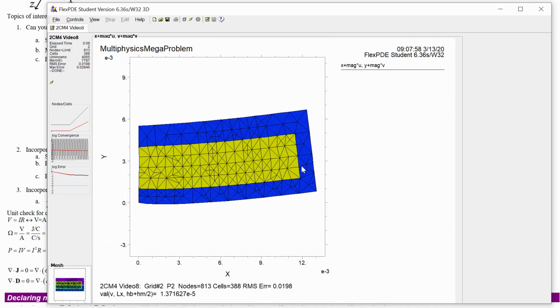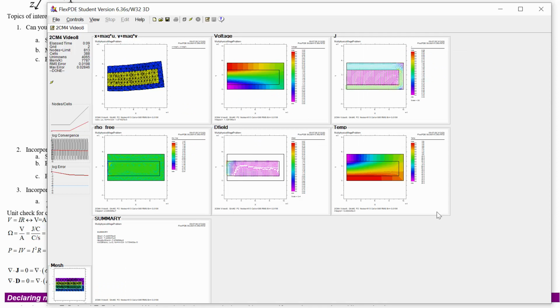The reason it bends up, even though we don't have any alpha difference, is because now we've got a temperature difference. The temperature at the bottom in this particular setup was way higher because we said the only place to dissipate the heat is at this one edge. So that means the bottom part heats up more than the top and is going to be bending up as a result.